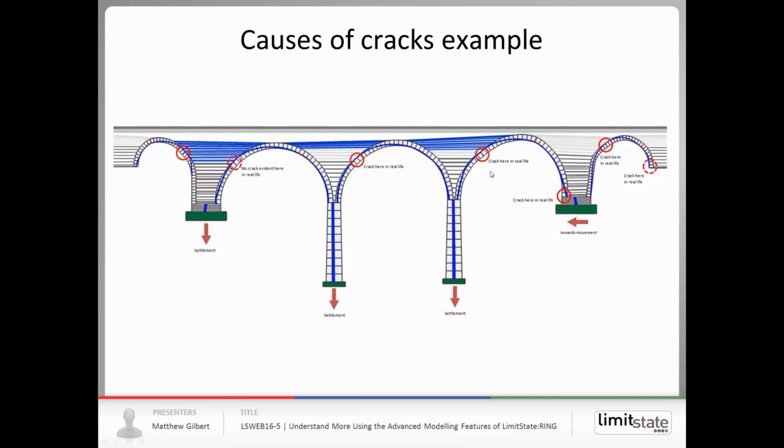And we actually found a very good correlation when we assumed that we have some translation of the right-hand king pier and downward settlement of all the other piers and abutments. So very close representation. In this particular case, we did use the deformed geometry in the analysis. So we modeled the as-is geometry rather than what we believe to be the as-built geometry.